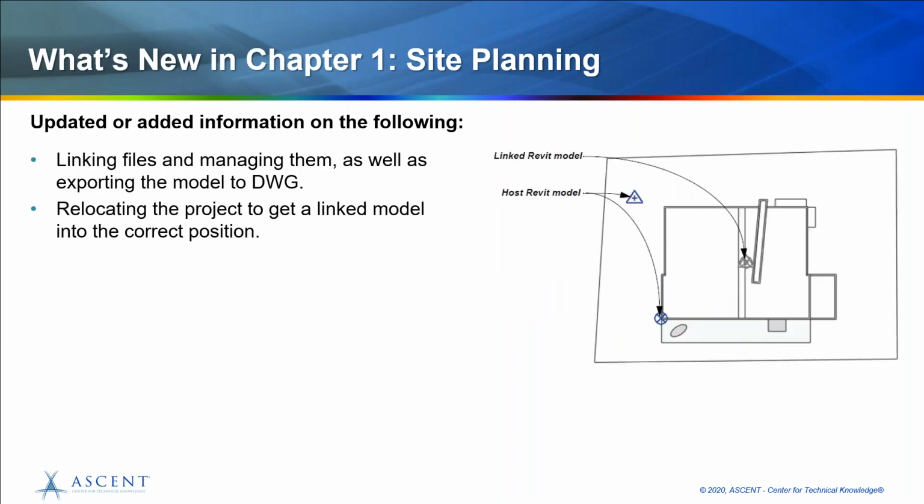When working with site plans, it is important to understand how to link and import files, as well as managing those linked files. And of course, exporting your model correctly for the surveyor or civil engineer with the proper units and coordinate settings. I have added repositioning linked Revit models and relocating the project. That was something that was important to understand, as well as just in your everyday common workflow.